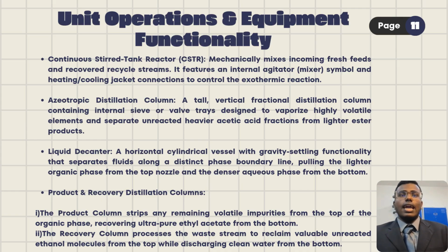The mixture then enters the liquid decanter. Here gravity separation occurs because the liquid phases have different densities. The lighter organic phase is collected from the top, while the heavier aqueous phase is removed from the bottom.